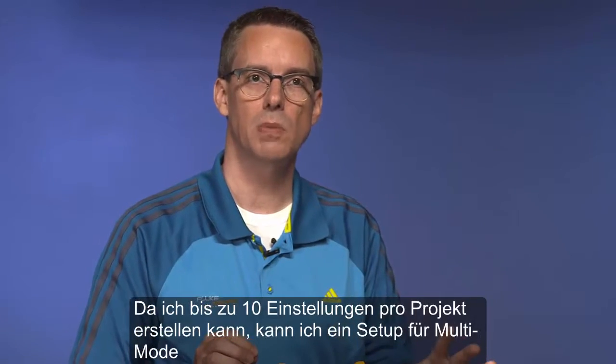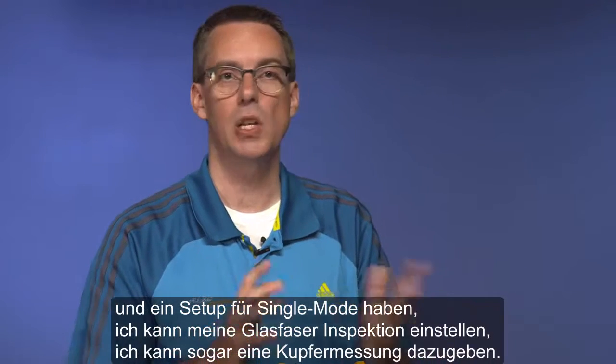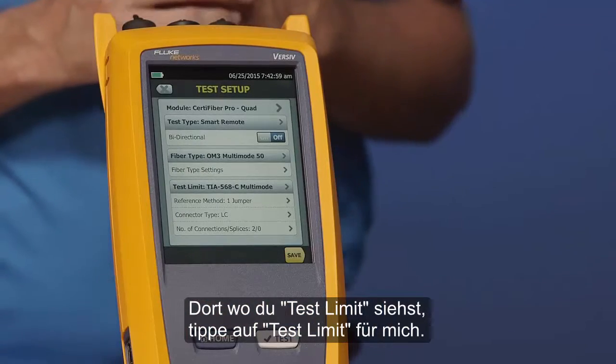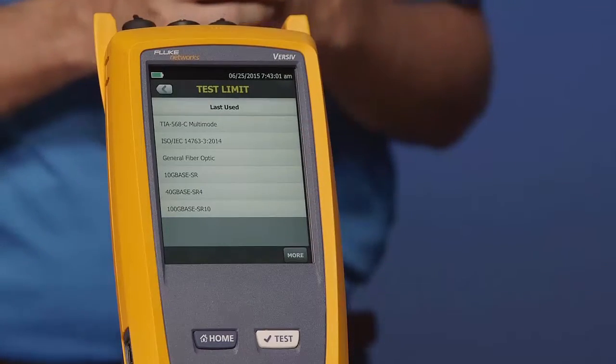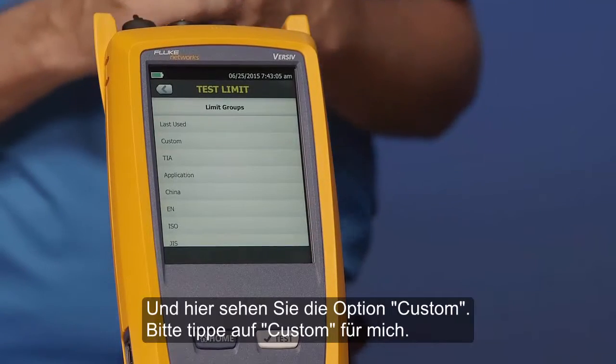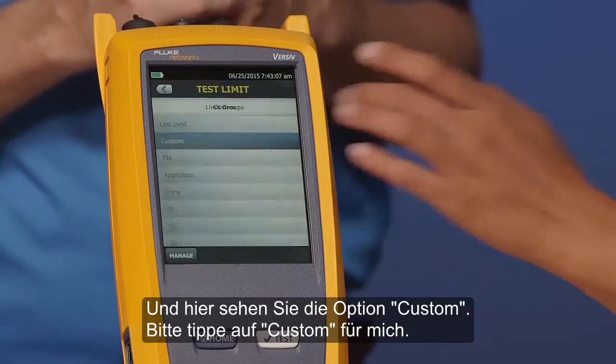I can have a setup that's multi-mode and a setup that's single mode. I can have my fiber inspection. I could even throw some copper testing in there as well. So where you see test limit, tap test limit for me and tap more, and you'll see the option that says custom. So go ahead and tap custom for me.